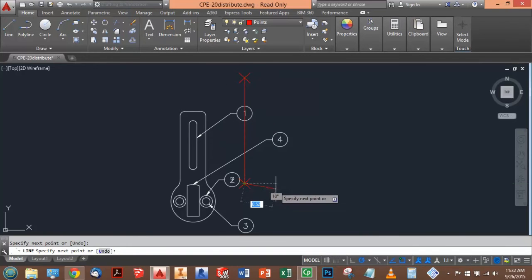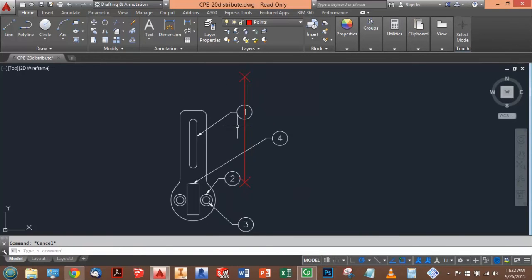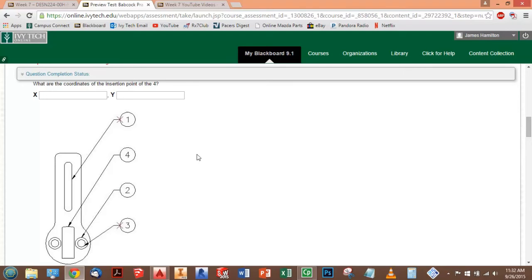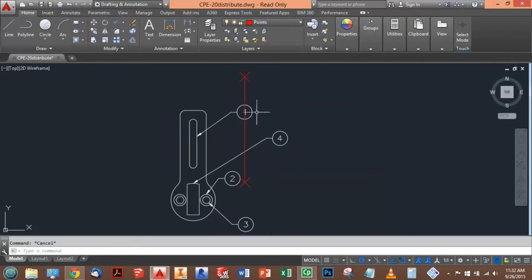So I'm just going to draw a line from there to there. And then I want to take this line, and you can see here that I want to cut it into 1, 2, 3 even segments. So that's what the divide command is great for, is it will take this and mathematically cut it into 3 even pieces, and then I'll have an OSnap that I can just drop these other ones on top of. So ultimately what I need to do is place this in the correct location. So I'm going to go ahead and just move these out of the way for right now.